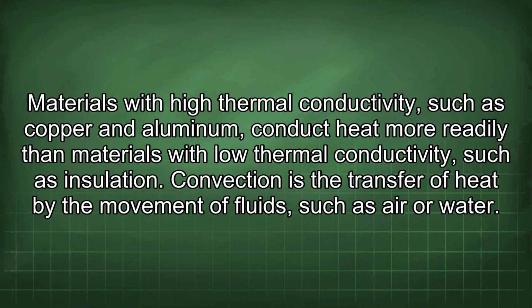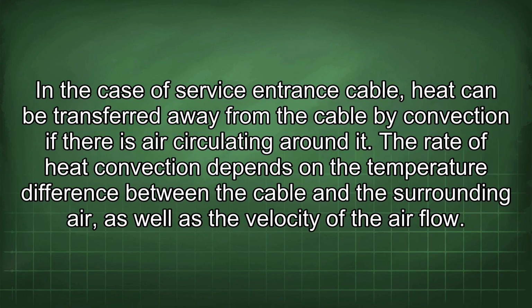such as insulation. Convection is the transfer of heat by the movement of fluids, such as air or water. In the case of service entrance cable, heat can be transferred away from the cable by convection if there is air circulating around it. The rate of heat convection depends on the temperature difference between the cable and the surrounding air, as well as the velocity of the airflow.